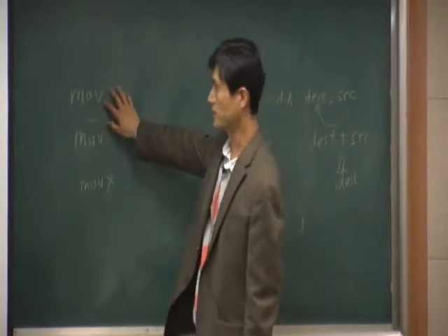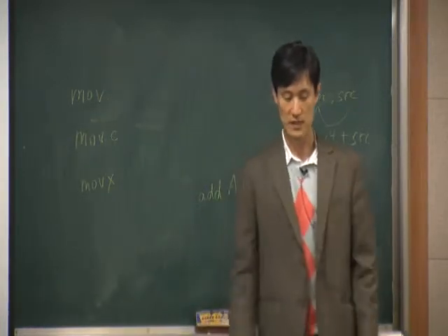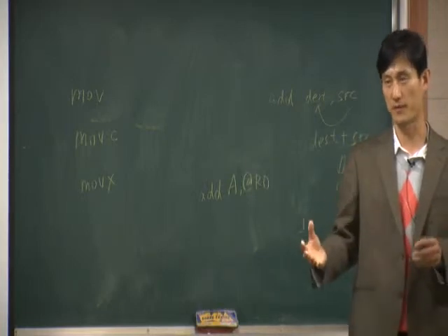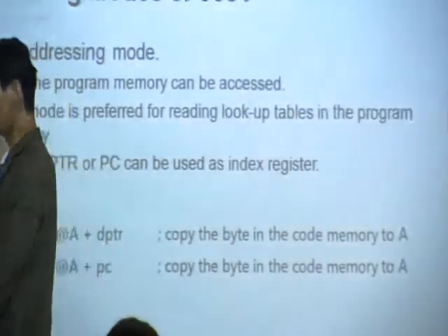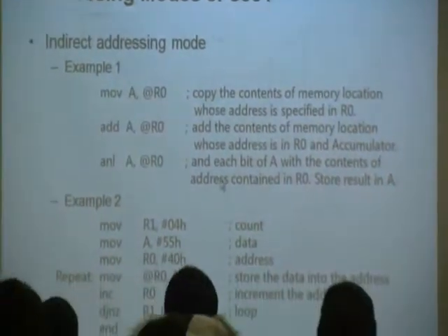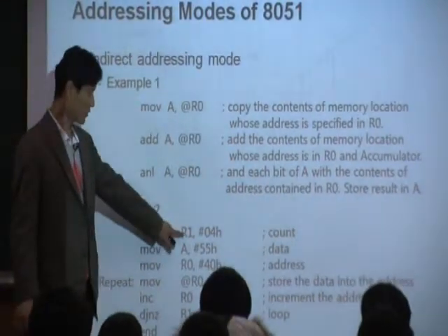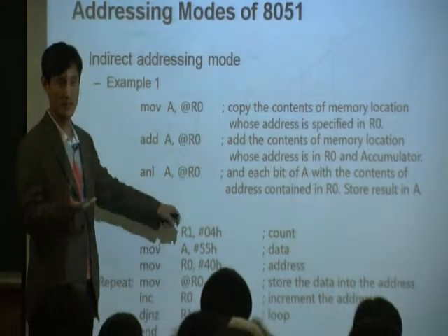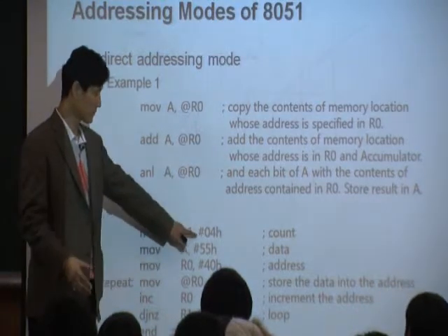This MOV, the first one, we always look at it, right? This MOV is like a copy between the internal memory. How do you know? Let's look at this one. We have a MOV R1. R1 is a register. A register is definitely an internal memory. You have a register inside the processor.